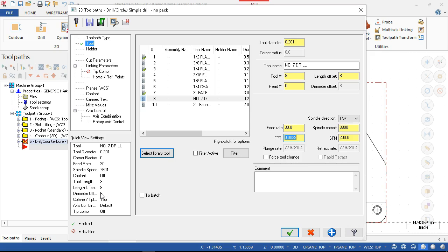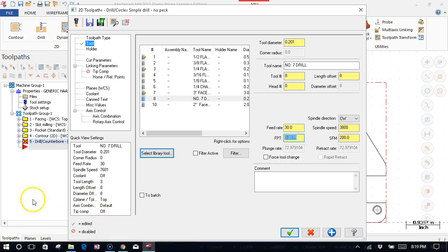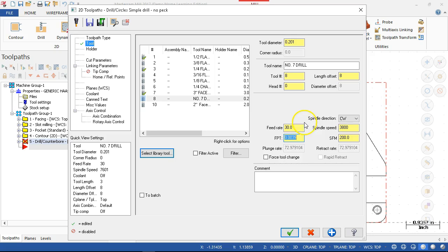When it comes down to it, we go to a carbide times 3 to 5. If we are reaming, that gives us another set of parameters. So we're juggling those numbers. One of the adjustments that I'm making is on this feed rate. I don't need this feed rate out to 3 decimal places. It's not doing anything for me. So if I see a nice feed rate coming across on the screen, that's something that I can manage. And if I have to change it, then I'll go F20, or I'll do something at the control to adjust it.